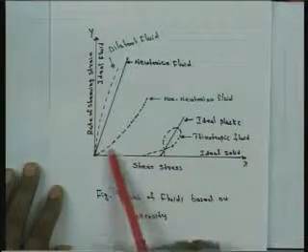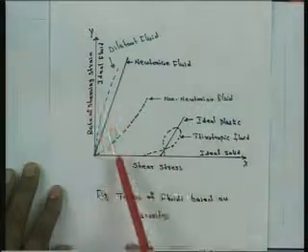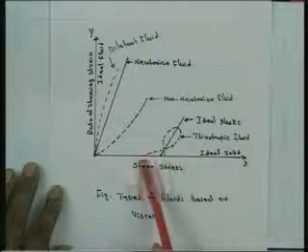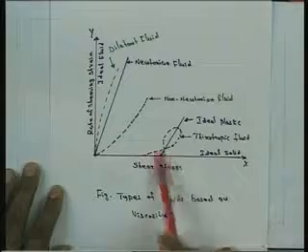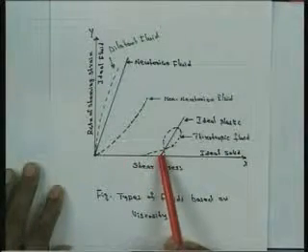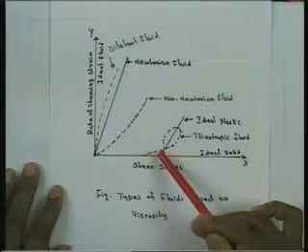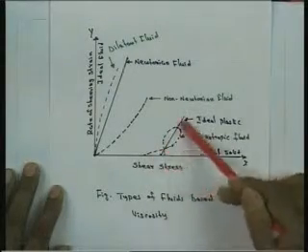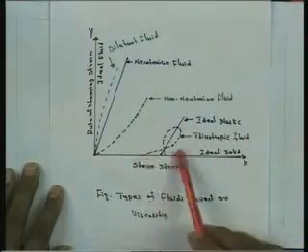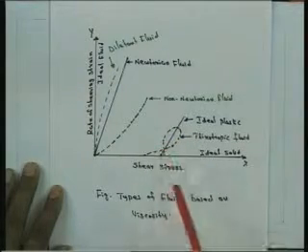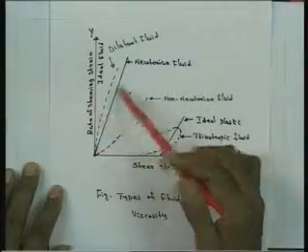And then if the rate of shearing strain starts only after application of a fixed quantity of shear stress, like here, say up to this point there is no deformation, that kind of fluid is called an ideal plastic. After reaching this particular point, the variation is linear. And then if the variation is again non-linear like this, then it is called a thixotropic fluid.